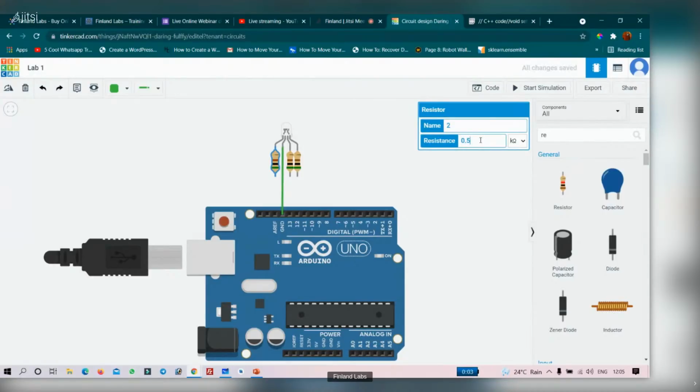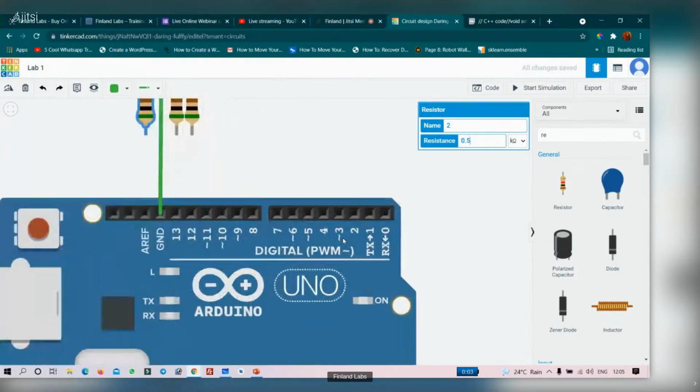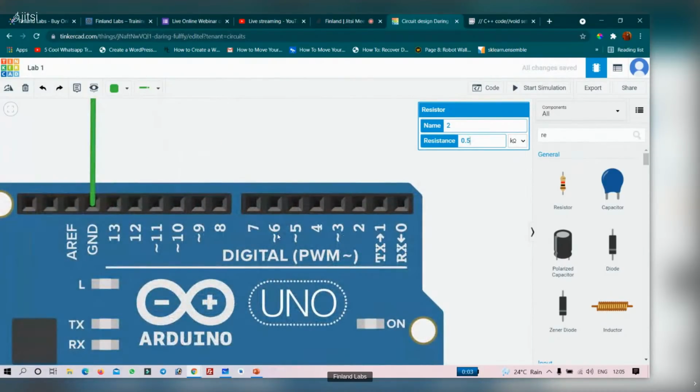Now see, if you are taking an analog output, you have to take an analog output pin, which is also known as a PWM pin, pulse width modulation. These are the pins related to pulse width modulation, where you can see this analog sign. Can you see the analog sign here? 3, 5, 6, 9, 10, 11. These are the PWM pins. So you can get the analog output on these pins only. If I connect to 2, you will not get it. Connect to 4, you will not get it. So you have to use these 6 pins only.